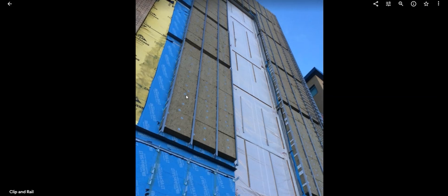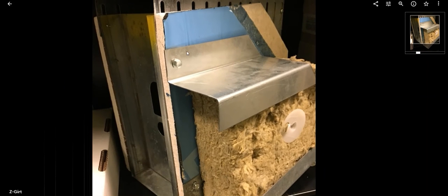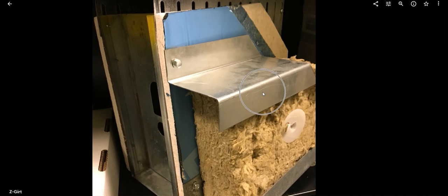That's gone away because of the current energy code. Now it's these clip and rail systems that are being used, because then you just decrease the conductance. If this was a continuous Z-girt, I might have a picture of that actually. Here's an example of a Z-girt. This is how it used to be, I'm going to say the 2017 energy code. There'd be a continuous metal Z-girt put through the insulation for the cladding to attach to. That's bad, obviously, because you lose a lot of heat through that metal.